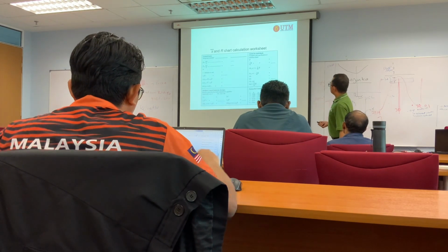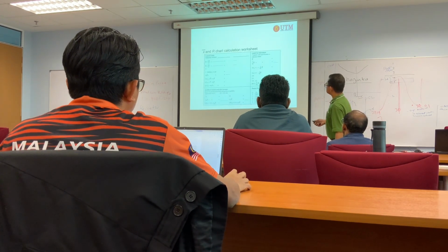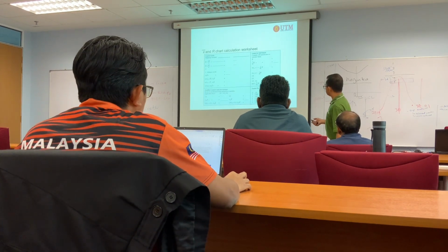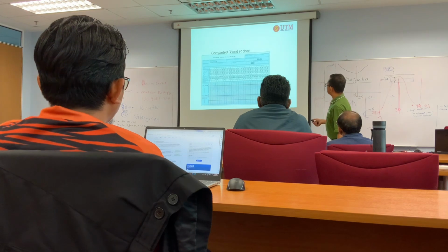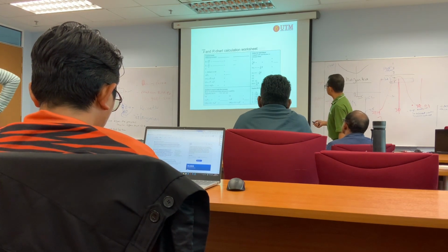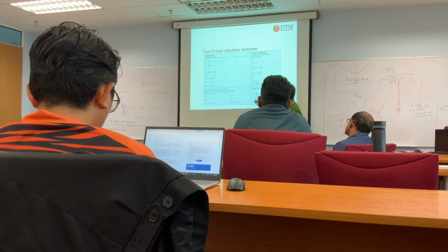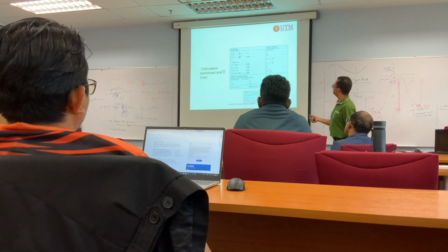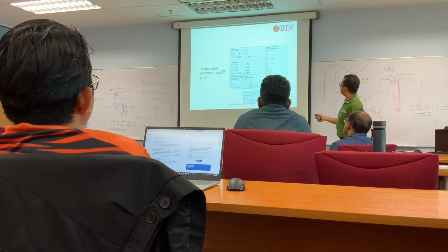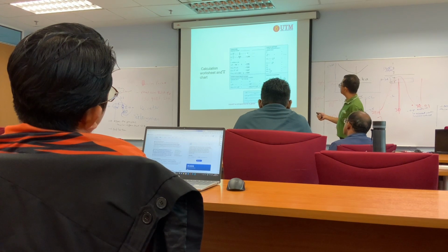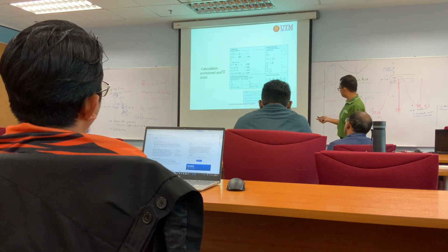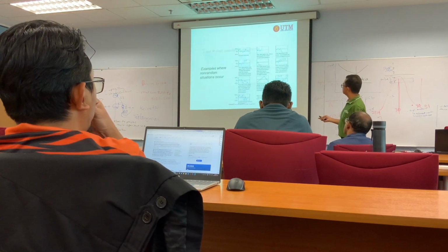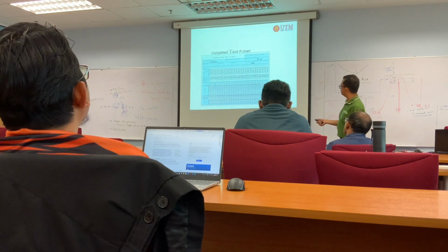Okay, so we go back to this one. So A2, because previously we have 4 samples for each subgroup. So for 4, we take 0.729. We got the R value, R bar, X double bar. So this is the answer. So the X double bar is 6.12, R bar is 2. So we have the value for upper limit and lower limit. This is how we do this. And then we have this upper limit and lower limit.